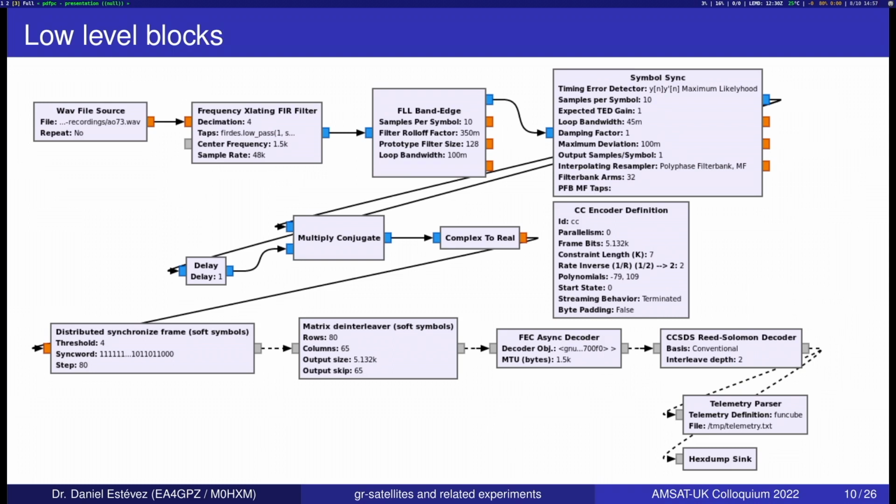And this is another way you can interact with the system. If you really need fine control, each of those two blocks we had, so the demodulator, now would be converted into a collection of blocks, which is the way of implementing a BPSK demodulator in GNU Radio. So if you wanted and needed to do something very specific, you could change some of the really low-level parameters here.